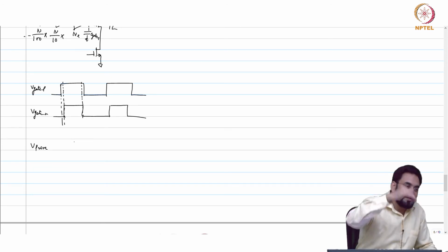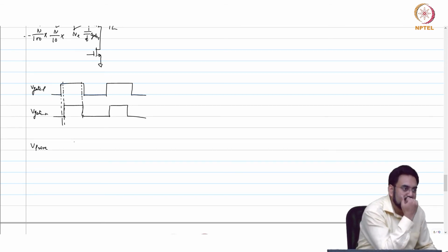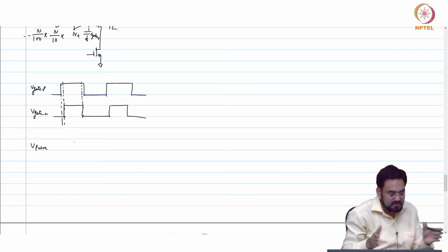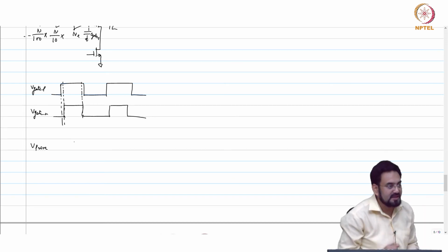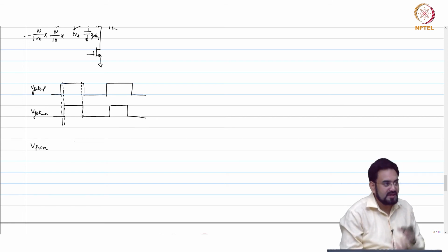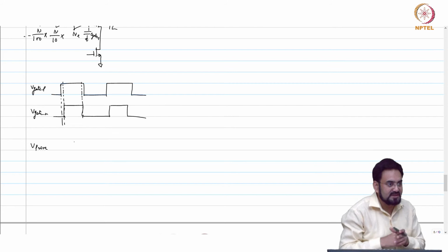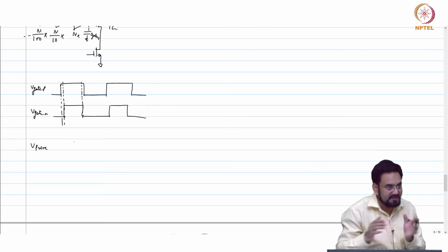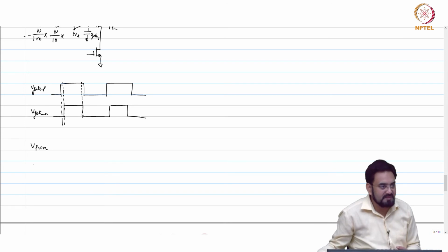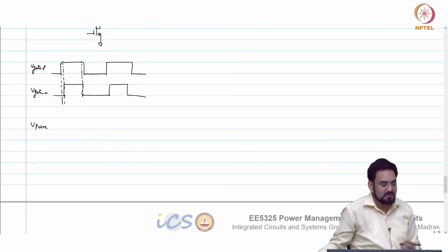In the same way, if PWM is going low, at a falling edge, you want PMOS to turn off immediately, but you turn on NMOS after some delay. That is how you introduce this dead time. So we have to build a logic where at the rising and falling edges, the devices turn off immediately but turn on after some delay, which means you need some kind of feedback to do that.